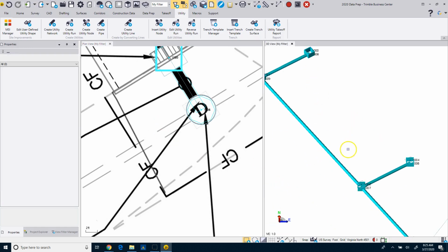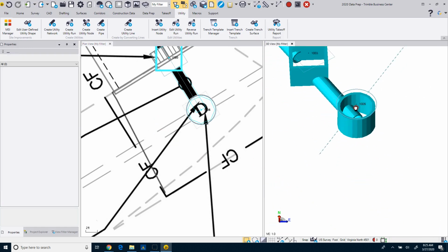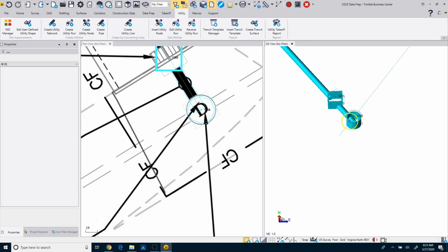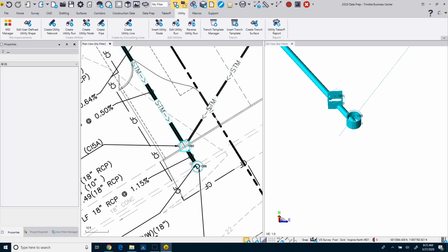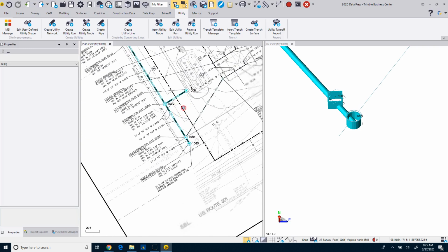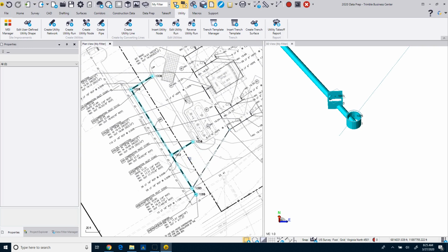So now when you look at it down here, I've got the manhole. So now I can come in and, like I said, I'll go through and I'll fix these and rotate them, and then set the rim heights. And then in the next video, I'll show you how, when you export this out, what results you get by exporting out a 3D pipe network.